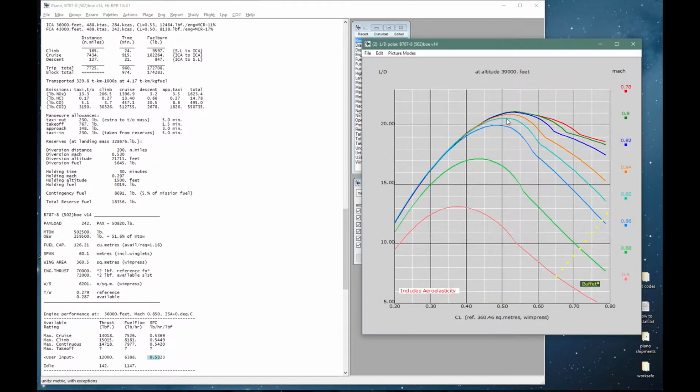Finally, let's look at the overall aerodynamics. Peak lift to drag ratio around 20.5 at Mach 0.85. Ignore the kink from the aeroelasticity adjustment. Now, I'm personally confident that this V14 drag polar is a very good approximation to the true aerodynamics of the 787, but as always it remains strictly a paper assessment. For our purposes, I will treat these aerodynamic levels as our target, and I will adjust the Lecture 6 plane to get close to this basis. So these are all the characteristics we'll be working with.